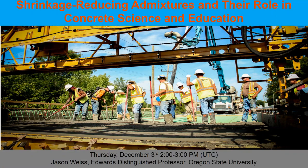What we're going to start off with here is a picture of a bridge deck, and this is a typical structure where you may expect to see shrinkage problems. One of the reasons for this is you have a very large surface area where evaporation can take place, and the concrete is usually fairly heavily restrained, which usually means that this is the type of structure that's very susceptible to cracking. So what we want to do today is talk a little bit about shrinkage, get into some of the basics of shrinkage, but then really dive into some of the things that shrinkage reducing admixtures can bring to the table.